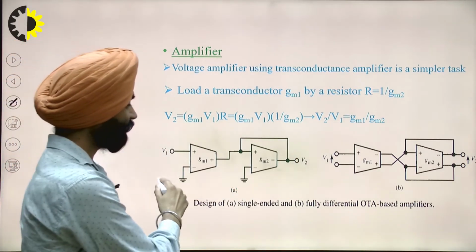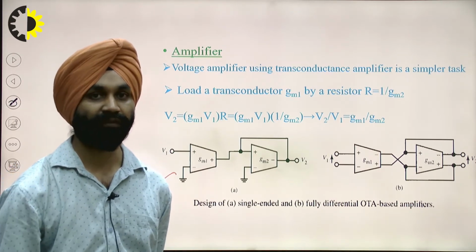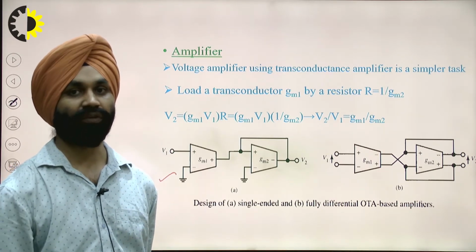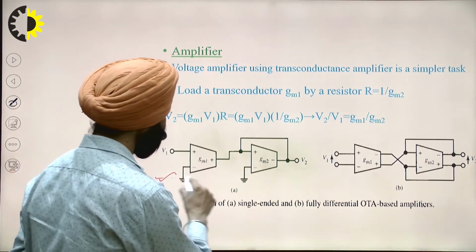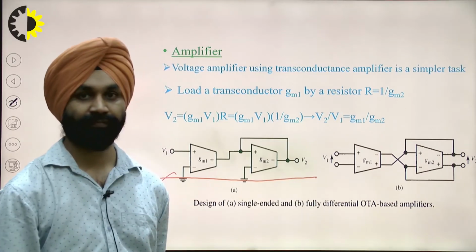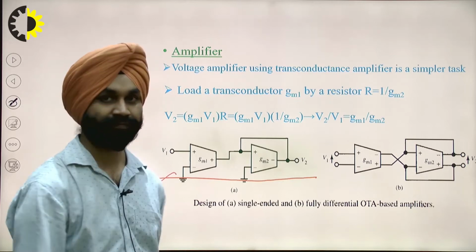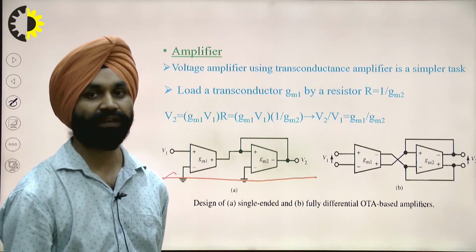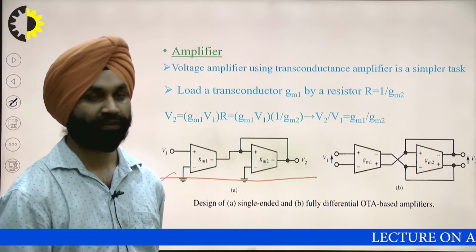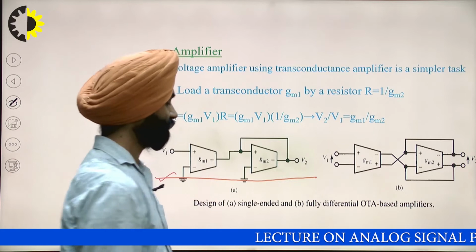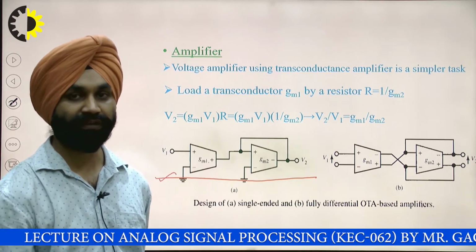This is a single-ended amplifier. Now, to make it a differential amplifier, we have to take a mirror image of this whole circuit. If I take a mirror image from the ground, then we have to connect the mirror image, and then I have to discard the grounds and merge the active devices. So this makes this circuit, where I have to take the inversion of the devices.